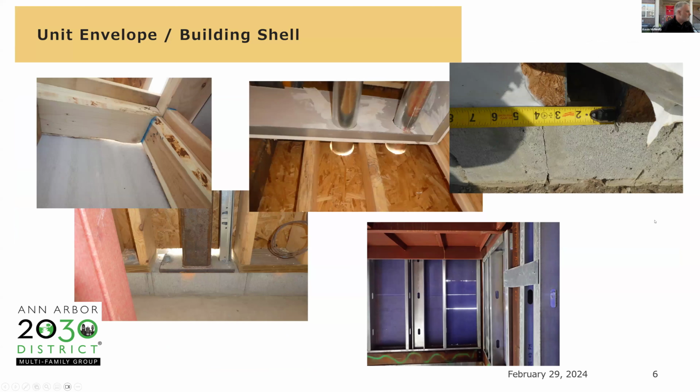And then here are all brand new buildings. So on this picture in the upper left, you can see air leakage. If you can see daylight, that's going to be a spot for air leakage to get into the wall cavity. Down here we have a structural member, and they notched around the structural steel. Our HVAC contractors obviously have to cut holes in the sheathing, but we need to get this air sealed up.